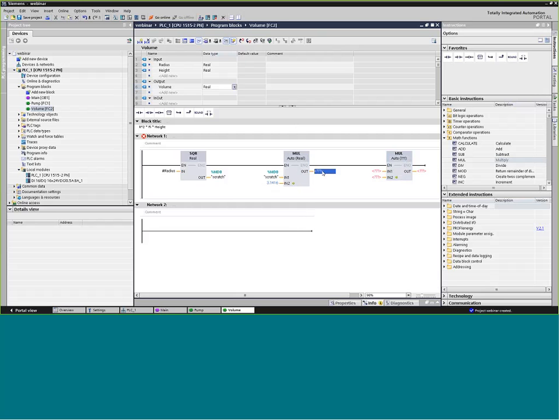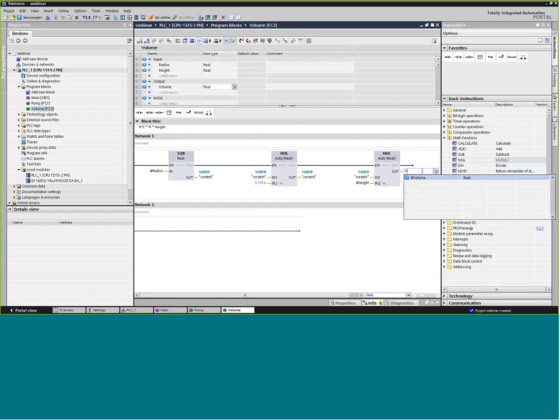So let's use our scratch again. We don't care about what was in it before, so anytime you write to it and read it immediately, that's a perfect example of a scratch. So I'll hit scratch there, pass that in to our multiply block, multiply that by the height, and our result is the volume.